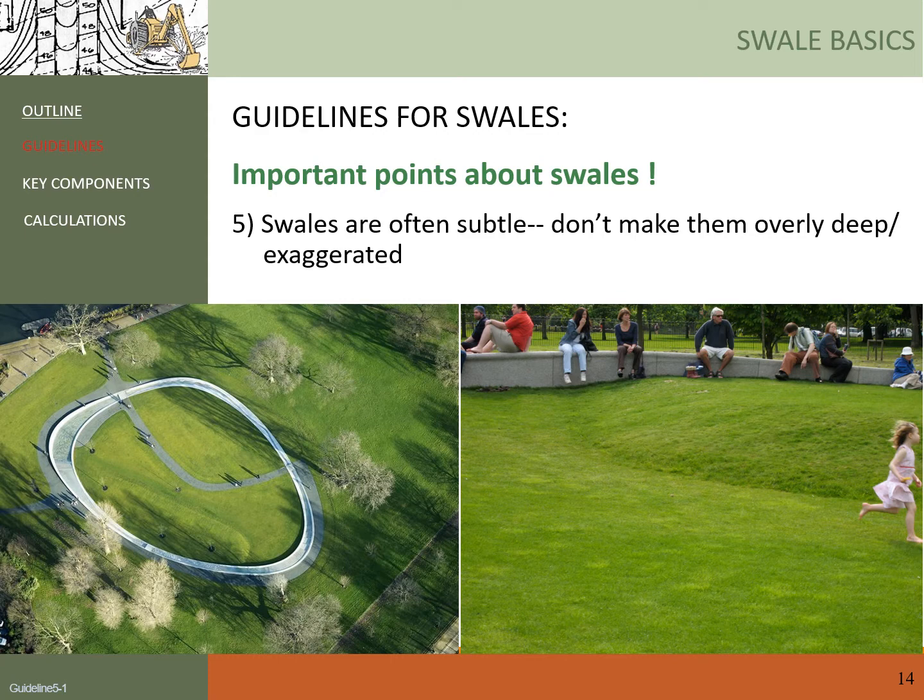Now the fifth point. Swells are often subtle. Don't make them overly deep or exaggerated. In most cases, swells will not be that deep or obvious. In some cases, swells won't be obvious until they have flowing water in them. When swells become deep, you'll start to have more restrictions on what you could do on that land, right? Also, steep side slopes encourage erosion and are more difficult to maintain.